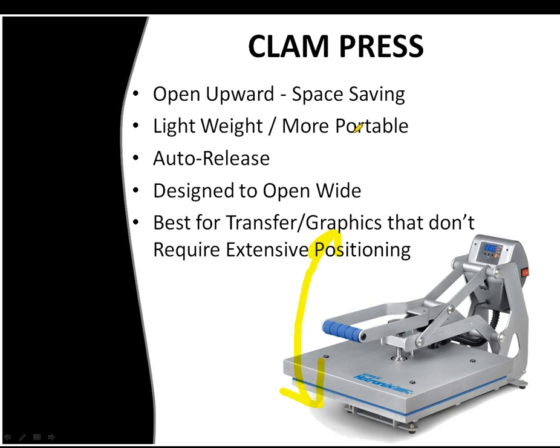A lot of clam presses offer an auto release option, and what that does is after your allotted time countdown has expired, your machine will automatically pop open on its own. And this is great because you can simply walk away and don't have to worry about scorching your garment or over applications, because as you walk away it's going to pop open for you.